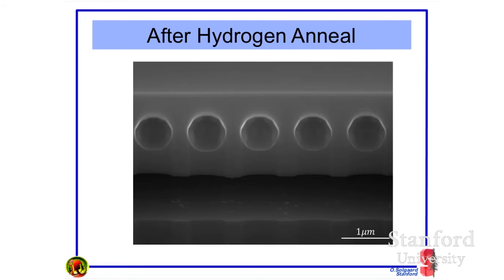Now I really have, this is actually a very good pressure sensor. We tested this in many different designs, because that set of small spherical voids on top becomes a photonic crystal that gives me high reflectivity. So we actually use an optical, interferometric readout to make this into a very, very precise pressure sensor. But the whole structure is made right there, and I think you would agree with me that there are very few limitations on what I can make in terms of shapes with this.